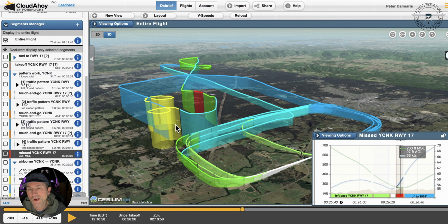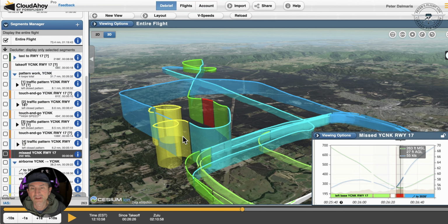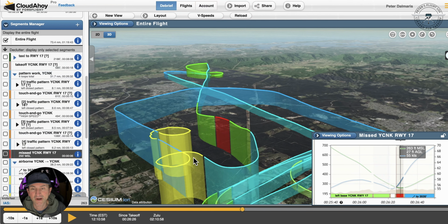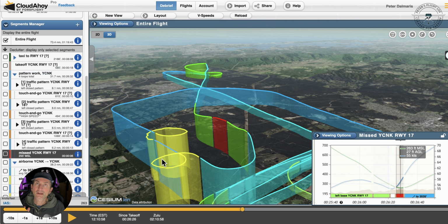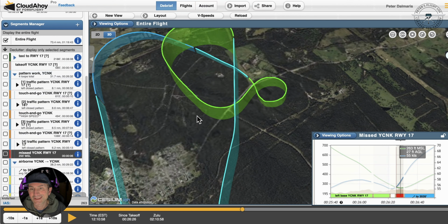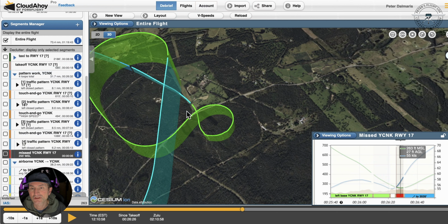The wind also plays a significant role in that, and that's why I think that spirals help, because spirals, especially if they're close spirals, can be more forgiving to the effects of wind pushing you away from the aerodrome more than you thought it would. If there's, say, a strong tailwind, it can push you too far away from your intended landing location, and then you just have to deal with a headwind. There's not enough energy left in the plane to get you there without an engine.